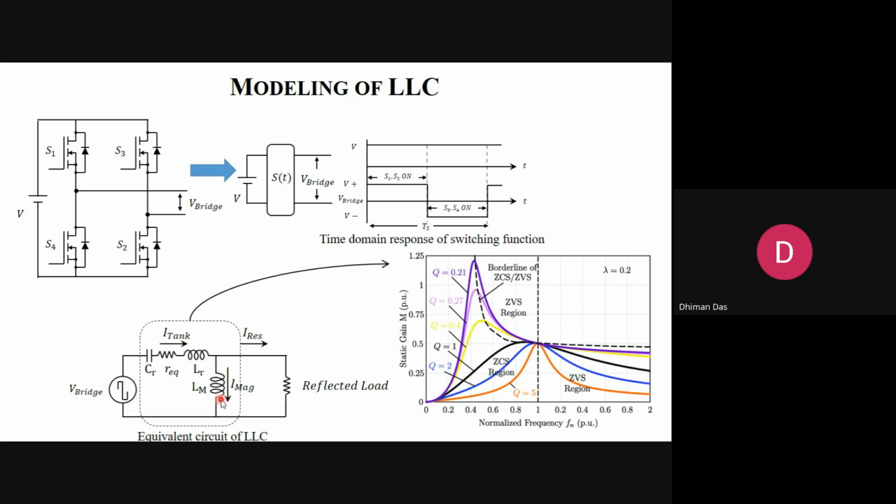So this reactive energy I take from the source instead of transferring it to the load, and feed it back to the source. This is quite a difficult mechanism for other converters, but in LLC this happens automatically. This is the beauty of this converter.